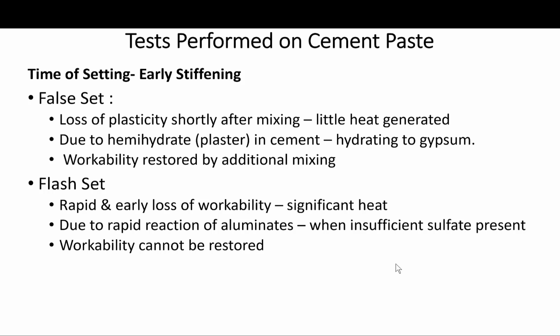However, the problem of false set will not occur with transit mixing, where the concrete is mixed for a long time before placing, or where the concrete is mixed prior to placement, as with pumping. The consequences of flash set are more severe and will usually cause the cement to fail to meet the time of set requirements, in the table I've shown earlier.